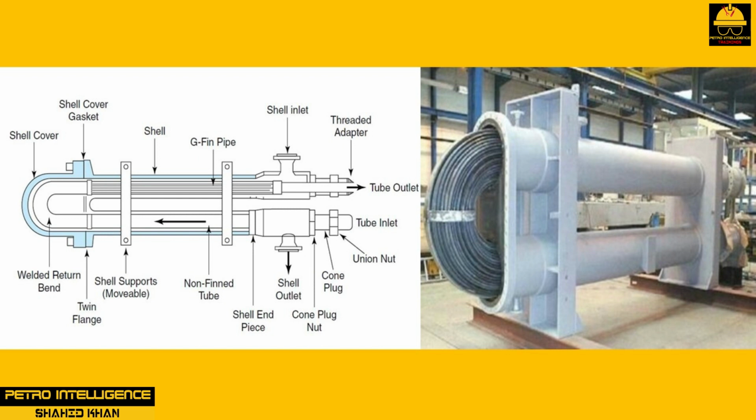Among its advantages are its excellent capacity for thermal expansion because of its U-tube type shape, its fin design, which works well with fluids that have a low heat transfer coefficient, and its high pressure on the tube side. In addition, it is easy to install and clean, its modular design makes it easy to add new sections, and replacement parts are inexpensive and always in supply.